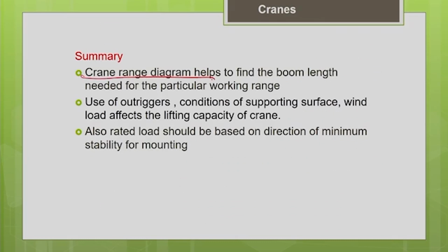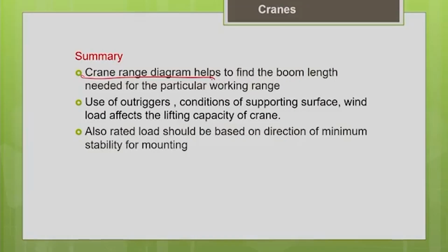So, we saw the importance of the crane range diagram. It will help you to find what boom length is needed for a particular working range, or what working range a boom length can offer. Either way, you can get the data from the crane range diagram. It helps to find the boom length needed for the particular working range.